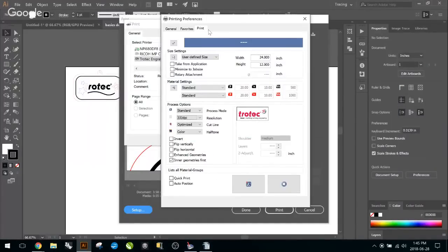Anthony, just a quick thing. Can you go back to, oh yeah, right where you are there. If you click on the color in the halftone option, most of you, if you're just starting on the laser, because this is the basics tutorial, it might be order dithering, which is just the black and the red, which is the standard. So if you're introducing a new color for kiss cutting or for whatever reason, and if you forget to change that to color, that's where 99% of the problems happen.